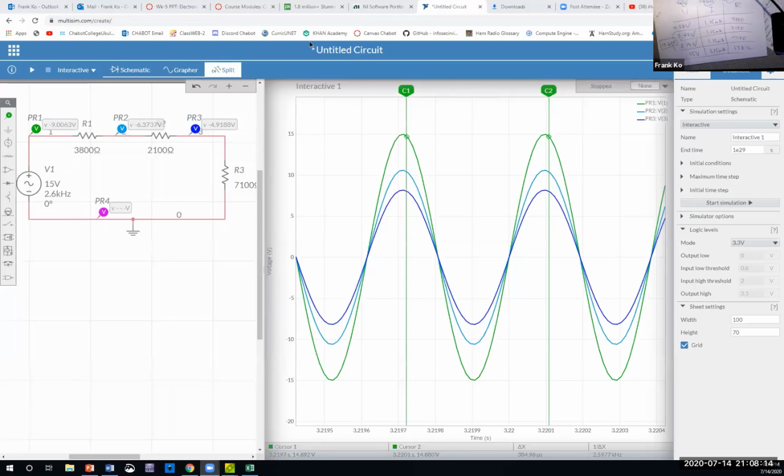In order to get voltages at specific points with respect to ground, we have to look at our circuit. So our circuit was an AC source. Here will be a resistor, a point. Here will be another resistor, a point. Here will be a last resistor, and we have ground down here. So we said that we would have 4.38 volts here, 2.42 volts here, and 8.19 volts here.